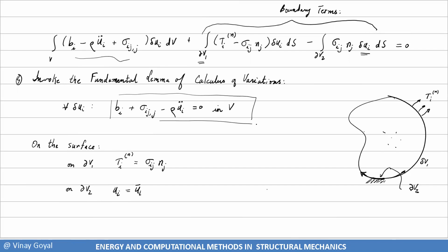Secondly, if you recall, I derived Cauchy's stress relationship using the tetrahedral element. And when I did that, it looked quite complicated. It took me a while to get there. Guess what? I got it naturally. I didn't have to even try hard. I just got it here. I got Cauchy's relationship here without even trying by using just Gauss's theorem, which is just a mathematical way of integrating by parts. Secondly, I automatically got the deflections, the displacements for this system.